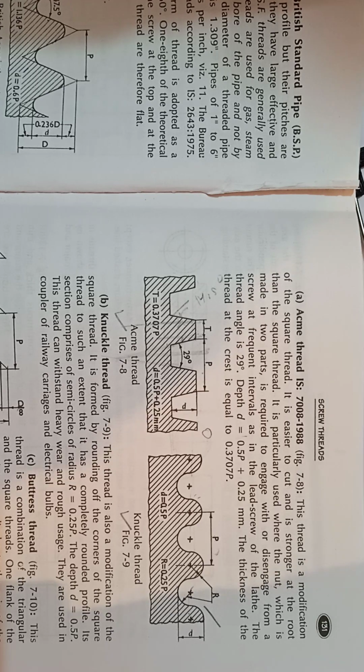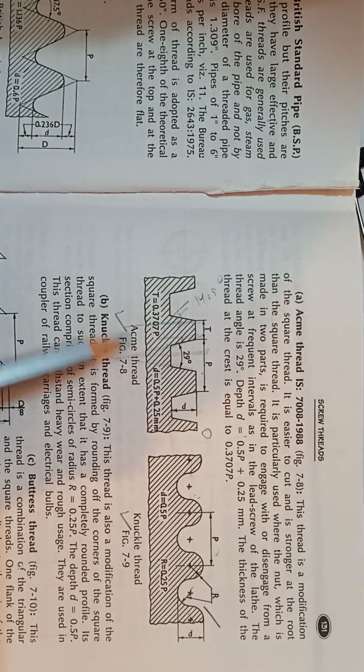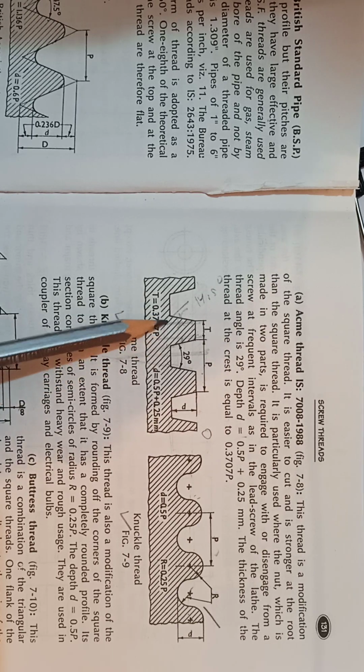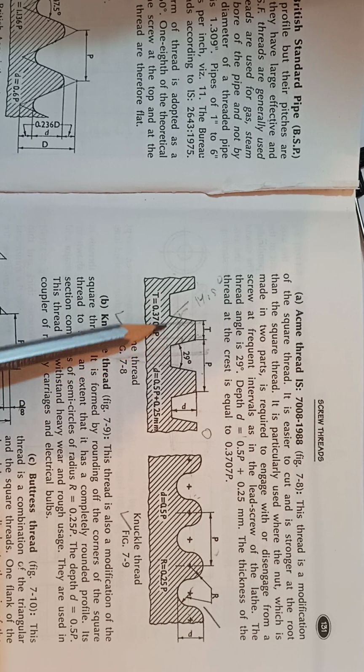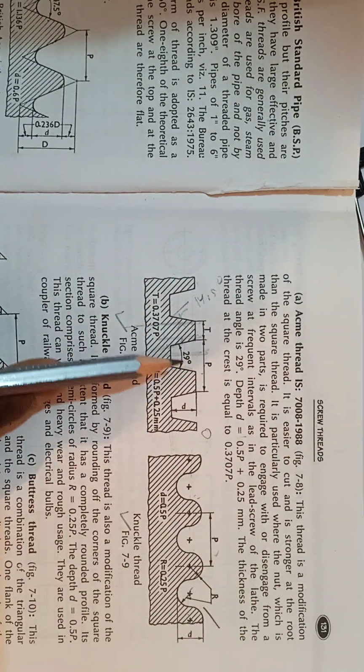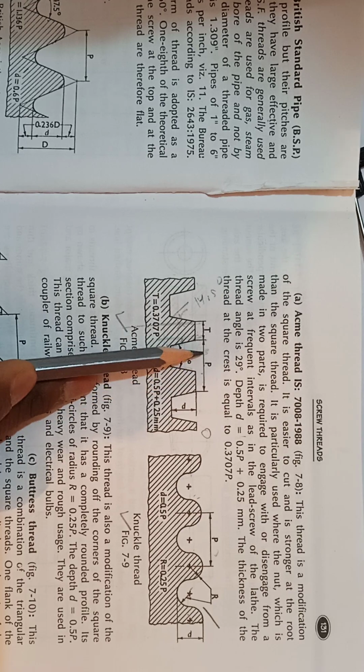So today we are going to draw the Acme thread. As you can see, this is the modification of the square thread. In our first class we learned how to draw the square thread, and now we have to draw the Acme thread, which is a modification of it. Acme thread is stronger than the square thread. Here the width at the core of the thread is larger than the square thread, so it is stronger. This is the pitch, this is the thickness,